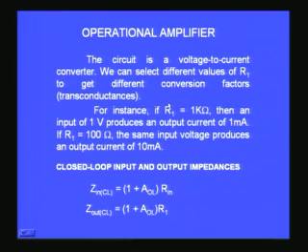For example, I have a thermocouple. So if I have a thermocouple, it produces a voltage, thermo EMF, corresponding to the temperature difference between the hot and the cold junction. This voltage I want to measure in terms of a current, so that I can have a thermometer, an electronic thermometer.